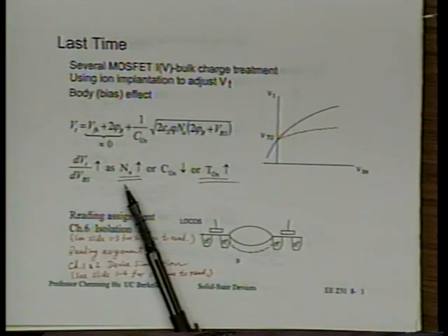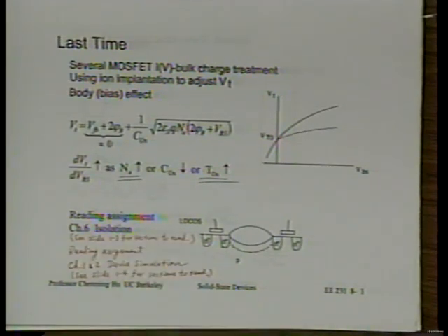Not that you deliberately create it, but just because of the way the current flows in the substrate, the IR drops can forward bias the substrate and the source. When that happens, your field threshold voltage can drop by many volts, and you will lose your isolation, and the circuit can fail. So these are the cases when body bias causes unusual problems, all right?